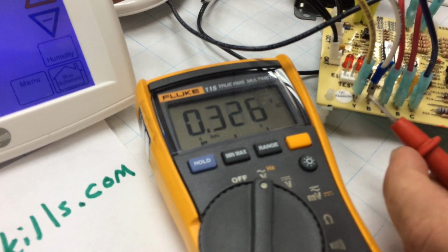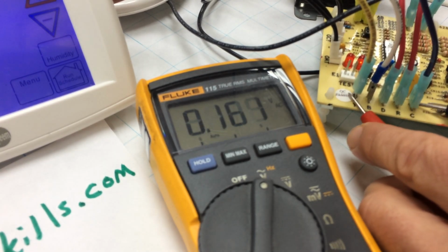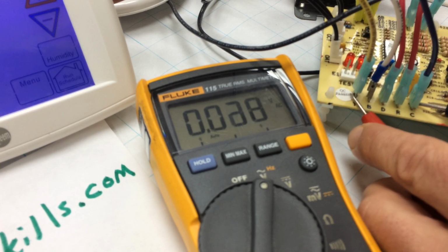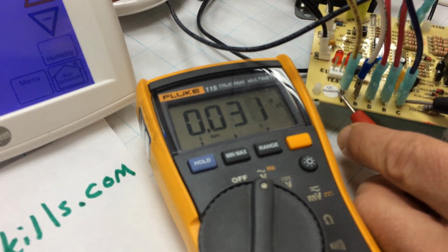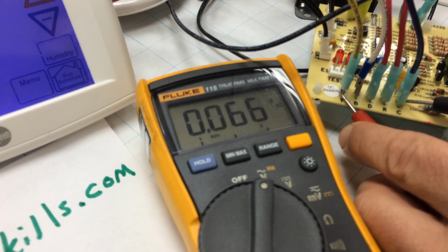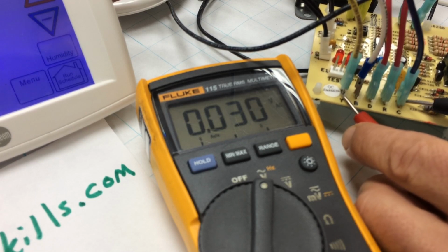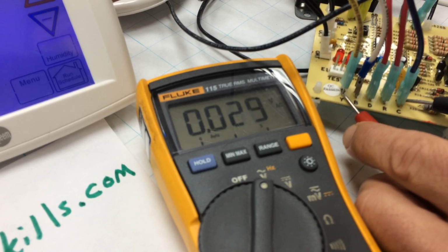this is where the ghost part comes in, because when I plug them onto control and now check the very same wire points, I have gone back to 0 volts because the signal that we thought we saw really is not there. This particular voltage is due to something called a Snubber circuit, and honestly the subtitle of this video should be always leave the wires connected to the load device when you're measuring the voltage.